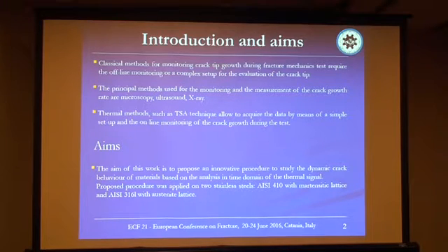And with thermal methods, such as thermoelastic stress analysis, we can evaluate also the crack tip position and the stress intensity vector with the same direct test with the infrared camera.